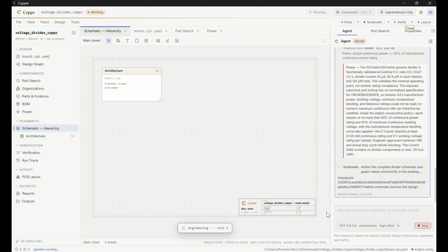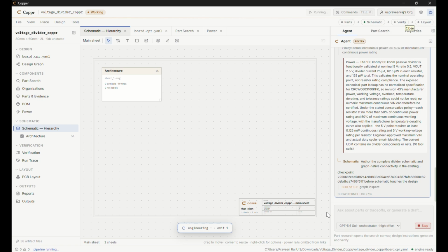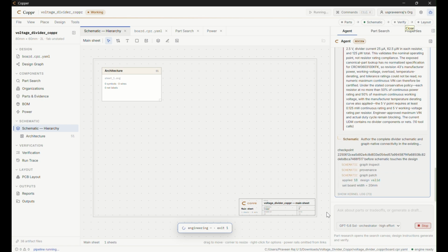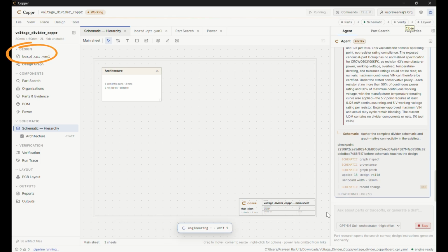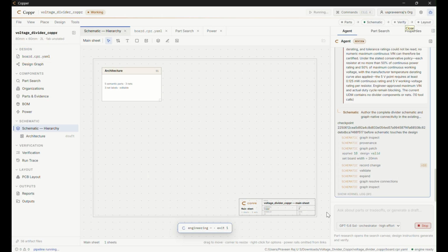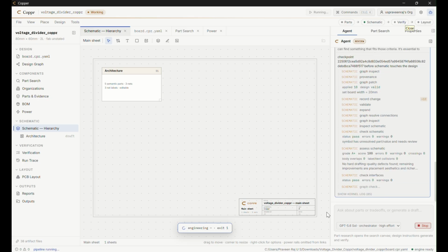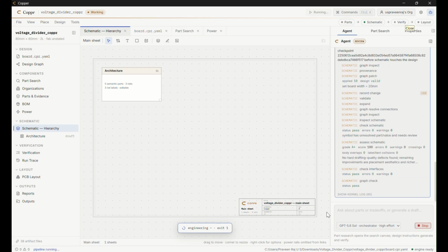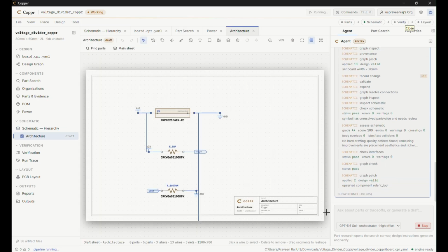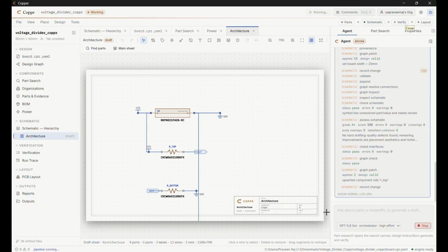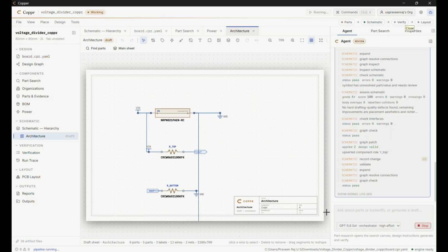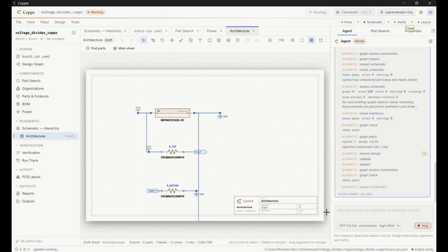With the electrical assumptions checked, Coppr moves to schematic design. It first creates the circuit structure from the typed model or code representation, which is the Coppr design language, or CDL. The input connector, the 2-resistor divider, the output test pad, and ground, and their nets are all first designed and expressed in code, and what the user sees in the schematic sheet is the editable projection of this CDL code. Now the first compiled preliminary schematic is visible.